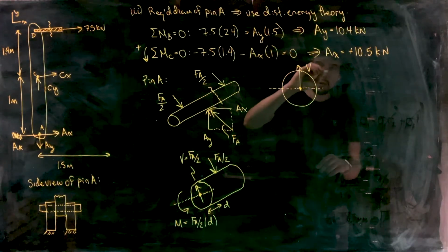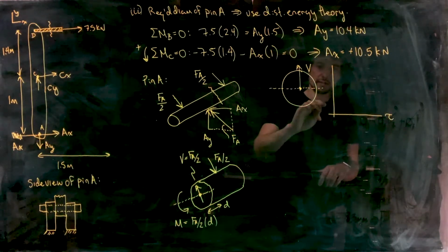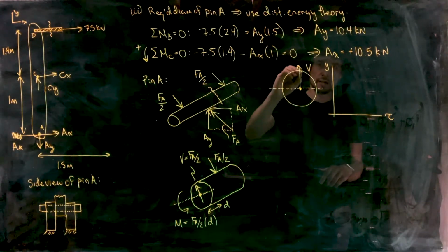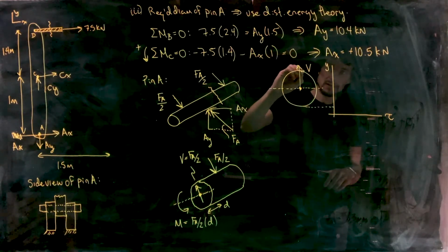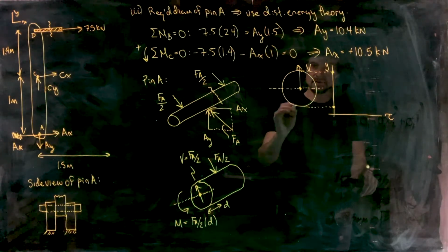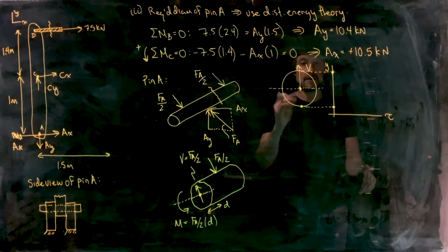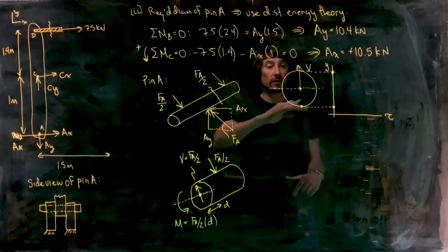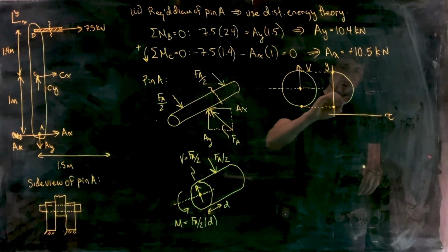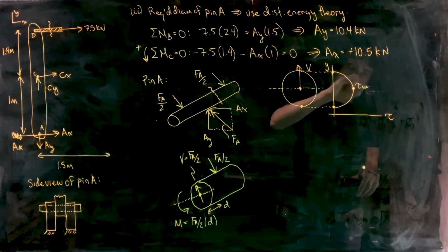So remember, if we're plotting the magnitude of our internal shear stress versus, let's say, height position within the cross section, distance y, for example, then our distribution of shear stresses looks like this, where we've got 0 shear stress at the edges, because if you take a location here and calculate the value of A prime, the portion of the cross section below that point, or a line going through that point, it is 0. And then the distribution of shear stresses will increase, reaching a maximum at the location of the centroid. So tau max there.